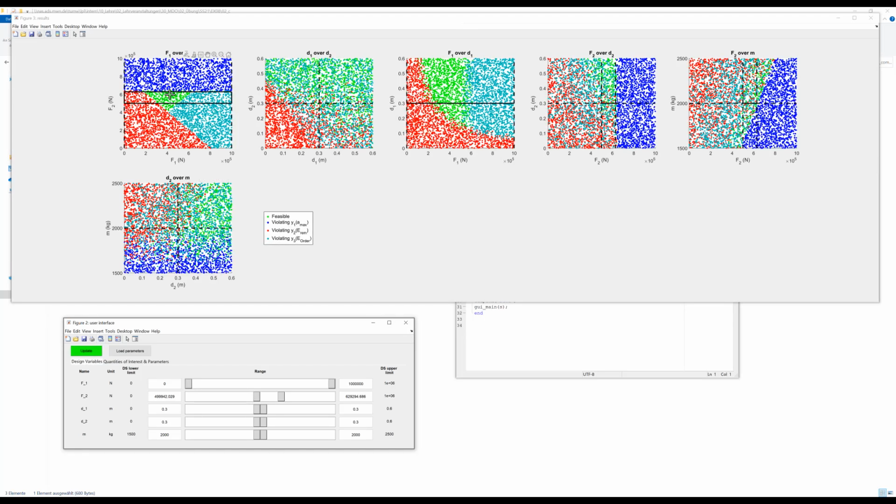So I think we got it quite well. Now we narrowed down this interval, and you can see in the other diagrams that green dots are appearing because we are getting closer to good designs. So it also has an influence on the other projections, of course. And now we still have to adjust F1, so we will go to, let's say, something about 3 to 5.